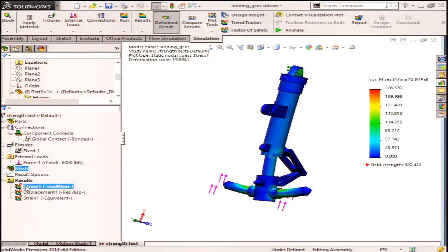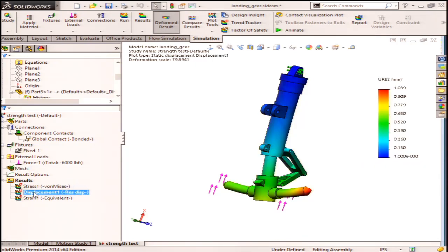All right, so here's our stress. Remember, stress is actually the third thing that we're solving for. So if you want a very, very accurate answer, you want to look at the displacement. There are instances where, if you keep refining the mesh and you're taking measurements of the stress, you'll find that your answer is never converging. It's never leveling off. Does anyone know why that might be?